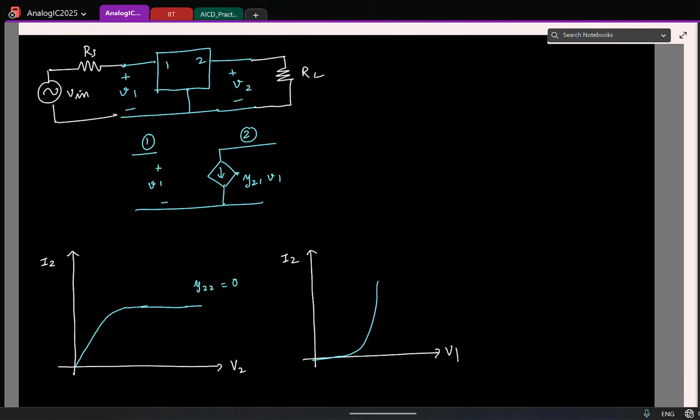And it turns out for a MOSFET, the current at the input side is 0, so Y11 and Y12 are automatically made 0. That's because my input current for a MOSFET is exactly 0. And remember that it is not just the MOSFET. Any nonlinear device which has small signal Y parameters of this form, wherein you have large Y21 and all the other Y parameters really, really small, can be used to make an amplifier. And it turns out all transistors in general satisfy this property.